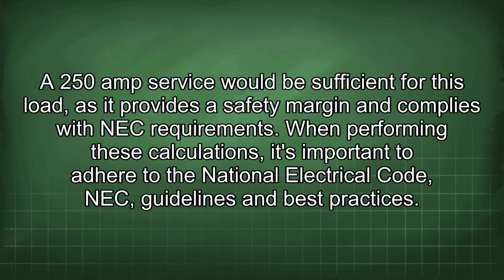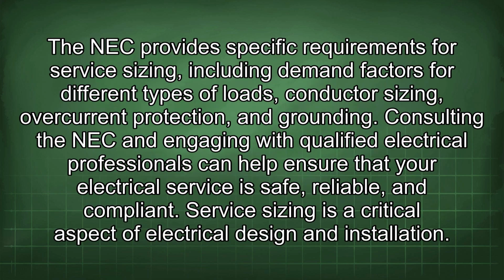When performing these calculations, it's important to adhere to the National Electrical Code (NEC) guidelines and best practices. The NEC provides specific requirements for service sizing, including demand factors for different types of loads, conductor sizing, overcurrent protection, and grounding. Consulting the NEC and engaging with qualified electrical professionals can help ensure that your electrical service is safe, reliable, and compliant. Service sizing is a critical aspect of electrical design and installation.